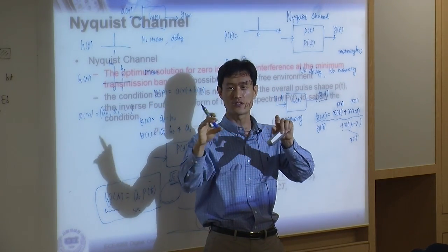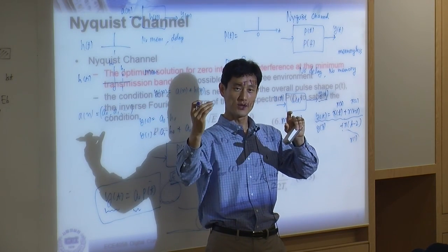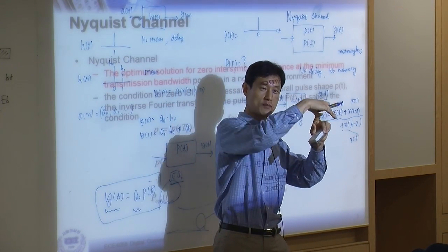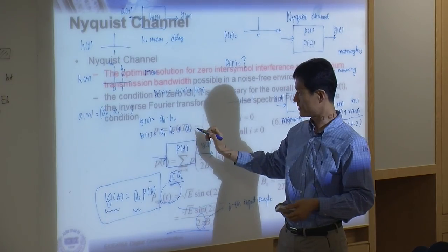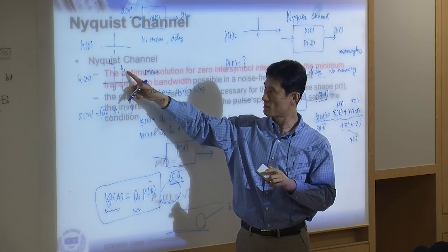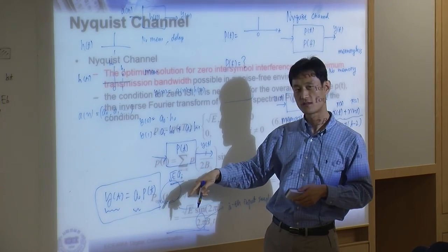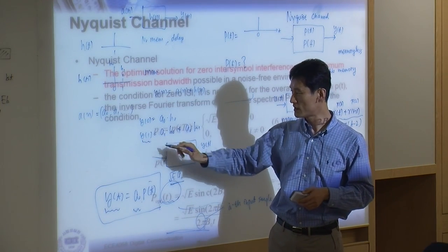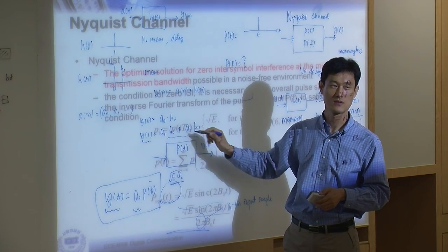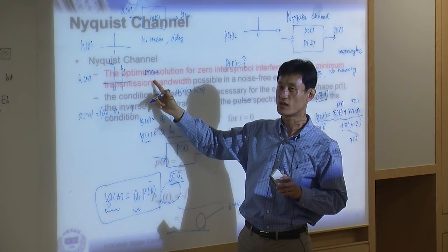Think about the shift register. You know shift register, right? This is exactly the same as a shift register. When you get an input, then on the next sample, this sample moves to the next memory. That's exactly what it is. So the previous sample a0 remains in the memory, moves to the next, and is multiplied with h1. This is what's happening, and we keep going like this. So your output has ISI, intersymbol interference, because of this memory.